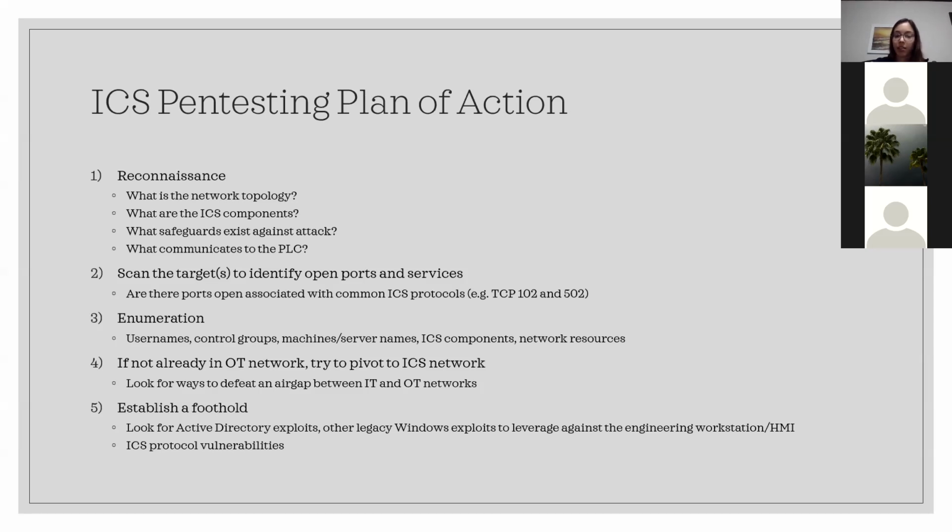The PLC is not expecting anyone to write to it right now. You could have alarms set up where if it exceeds a certain pressure, it'll automatically revert back to another pressure and it'll trigger an alarm. Things like that. So knowing those safeguards is very important.